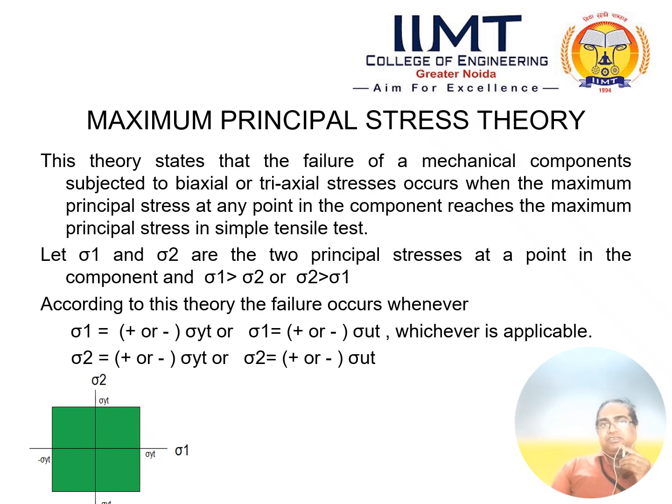This theory states that the failure of a mechanical component subjected to biaxial or triaxial stresses occurs when the maximum principal stress at any point in the component reaches the maximum principal stress in a simple tensile test.